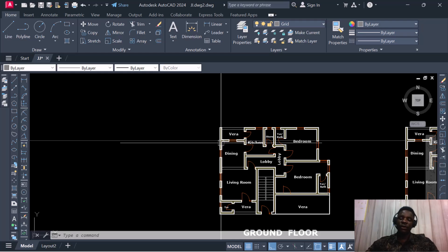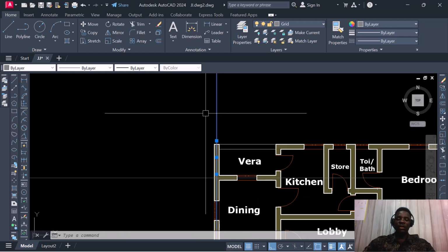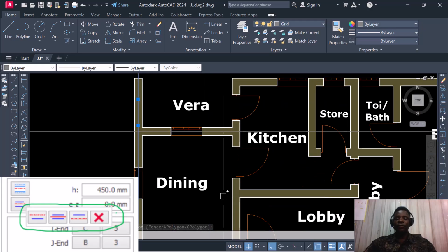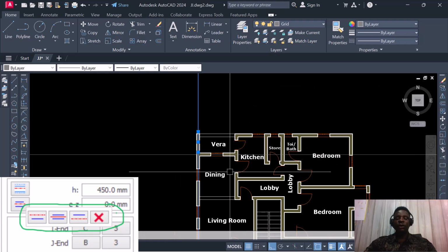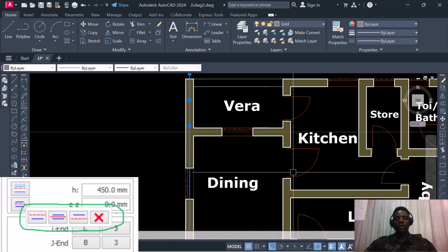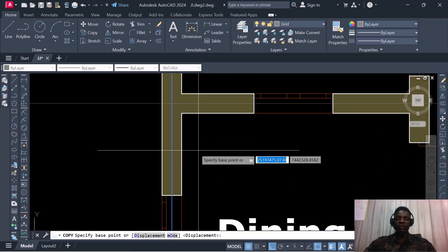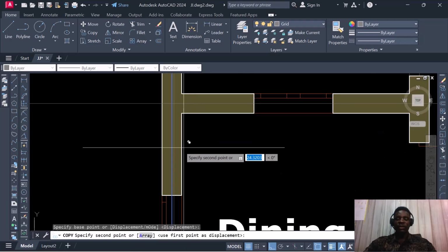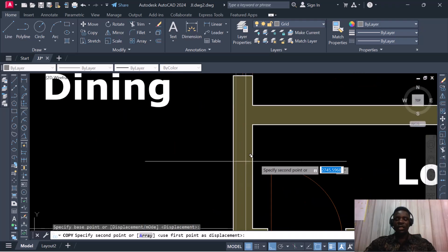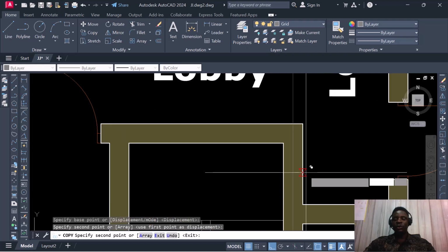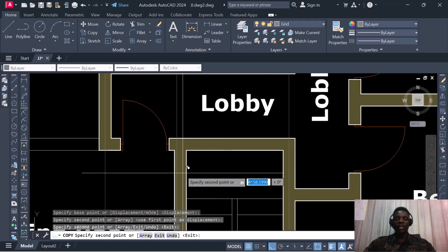Now this grid for this tutorial, I'll be taking it center to center. In some other video, you can also make your reference. You can take your grid by side of the wall, either side of the wall, either the front or the other end of the wall. So in this situation, we'll be taking it from the center of the wall. So now I'll be taking my reference from here, from the side. So in this situation, I'm going to be clicking all the portions whereby I'm supposed to have a grid. So I'm going to align the center to center of the wall.